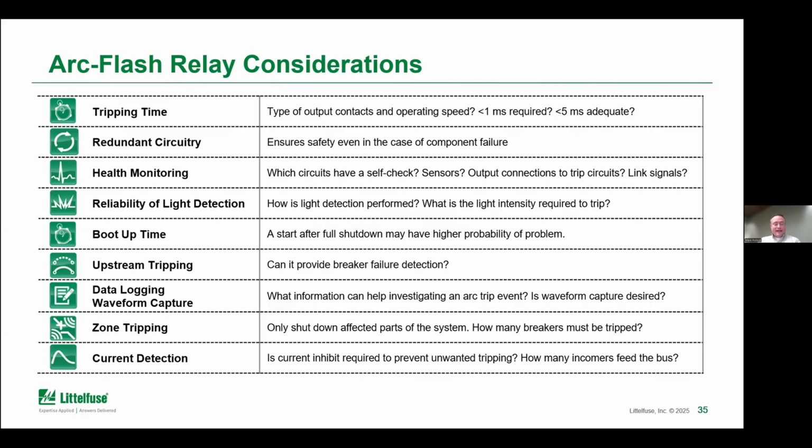Another one, looking at the data logging capabilities. So when you look at what investigation might need to be done after a trip event, how much detail is provided in that data log? And is that going to be enough information to help you look through and investigate that event after the fact? And is a waveform capture something that's required? That's not a standardized function in arc flash relays today, the same way that it is in a lot of the feeder relays using Comtrade or other platforms, but being aware of what data is available.